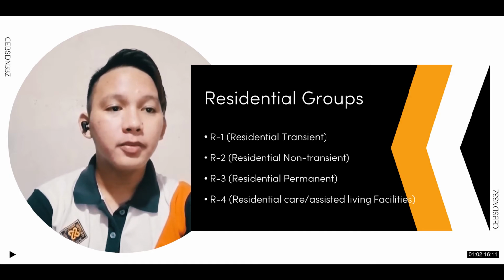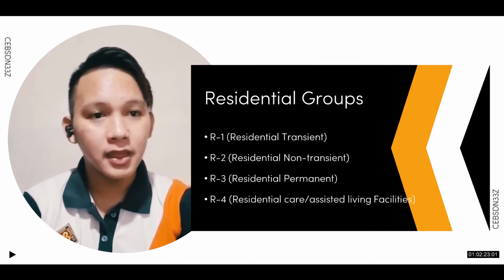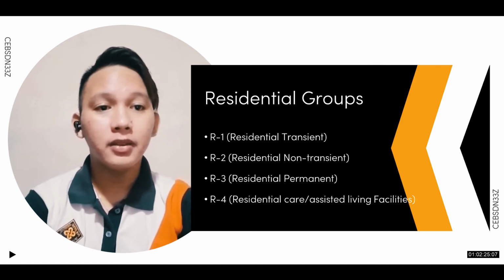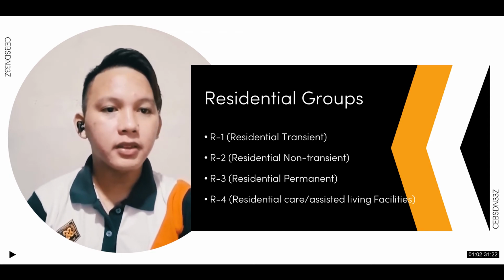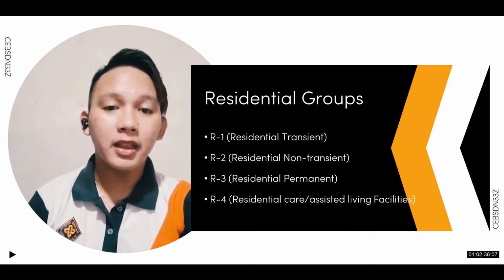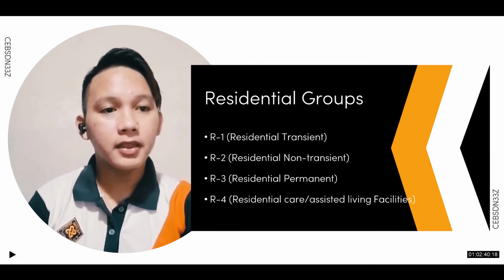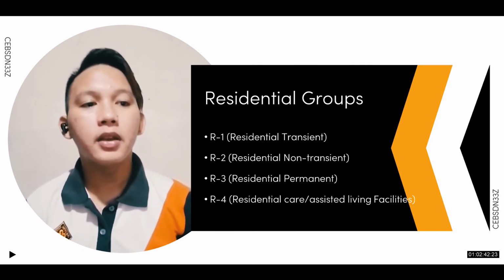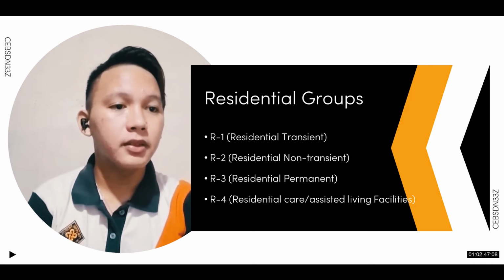Residential occupancies where the occupants are primarily permanent in nature and are arranged for more than 5 but not more than 16 persons, excluding staff who reside on a 24-hour basis, in a supervised environment and receive custodial care. The persons receiving care are capable of self-preservation. This group shall include but is not limited to the following: alcohol and drug centers, assisted living facilities, congregate care facilities, group homes, halfway houses, residential board, and custodial care facilities.